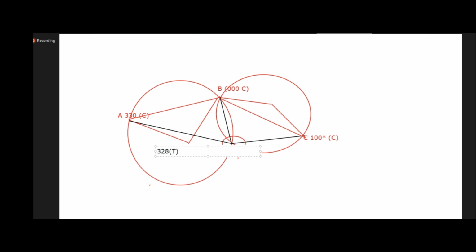We assumed that, sir. Yeah, I am assuming, but actually what you will do, from the P you put a parallel ruler and just move it parallelly and take on the compass rose what is the bearing. Suppose it is 328. And from the B, suppose you are taking 357 degrees true.